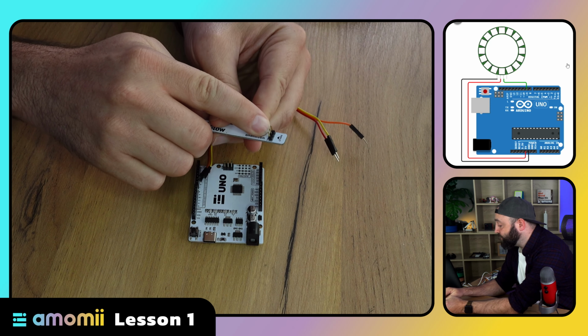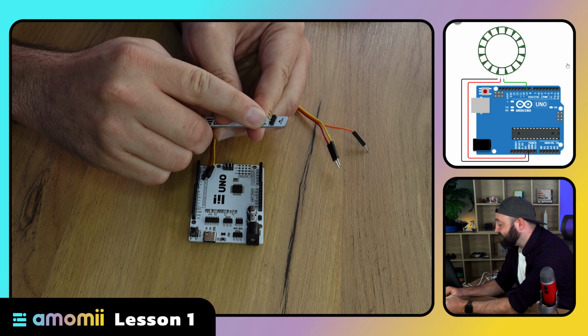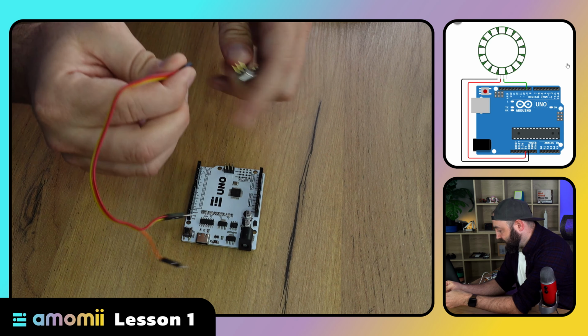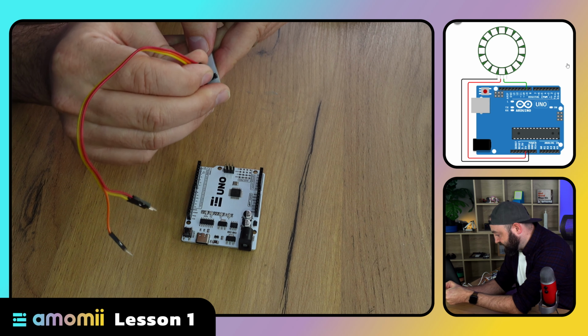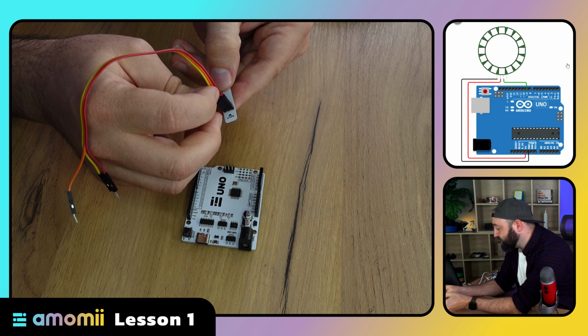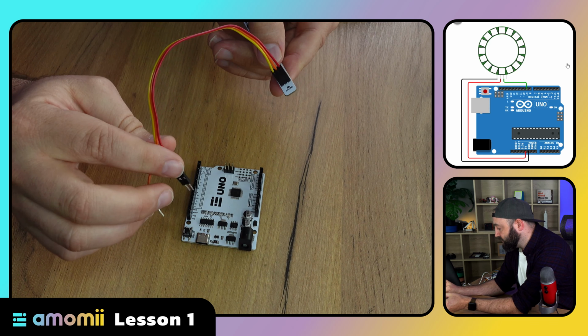We have a 5 volt pin, a ground pin, and a signal pin. I will just note which color is connected to which pin. I've got red going to 5 volts, I've got orange going to signal, and yellow going to ground.